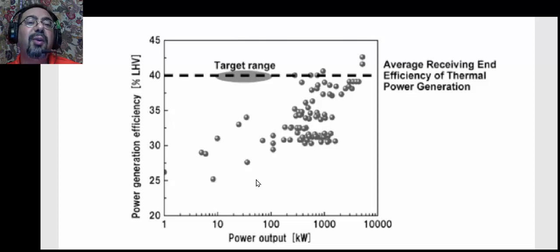So you move immediately from eta thermal to eta CHP, the eta of the combined heat and power system. So it will be Q plus P divided by F, right? So you will consider the heat as part of your output. So theoretically speaking, if we do this in our home, the efficiency would be 100%. I mean, of course, you will not recover all the Q, but theoretically speaking, you are above the Carnot cycle now.